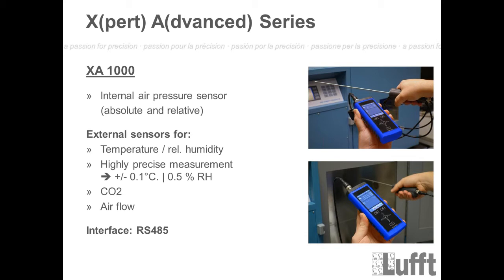For that reason, we have integrated on the XA1000 a digital interface, which is an RS485 interface. It is only, let's say, the physical layer that is RS485 here. That means the signals are transferred with this interface. But the protocol we use is a Luft special protocol, because often this is asked if you can also connect other brands of sensors, which is not possible here. Because we have our own protocols, we have to use special Luft sensors to connect to the XA1000.